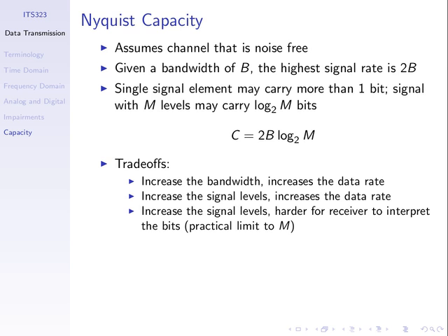Why? Because the receiver takes a measurement and compares it to one of the 4 possible values. Whichever one is closest, it assumes they're the corresponding bits. Maybe in this case we measure here, we're lucky, we get -6. Okay, the closest is -5, we're correct. Maybe in this case we measure at this point, we get +2. And therefore the closest level is this one. And therefore the bits that we get from this will correspond to this level, not the transmitted level. That would result in bit errors.